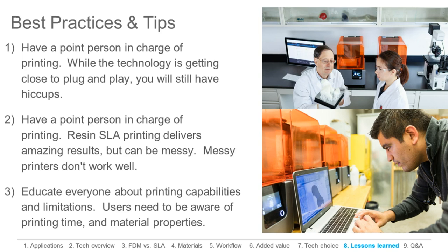As Lauren said, the different technologies will give you different types of parts. For example, with SLA, hollow cavities in your part can be a problem, and the same thing with powder printers, because wet resin will get trapped in there. That's a pretty easy problem to solve, but you want to be able to do that in software, and that's where having somebody who is an expert on it can really help.